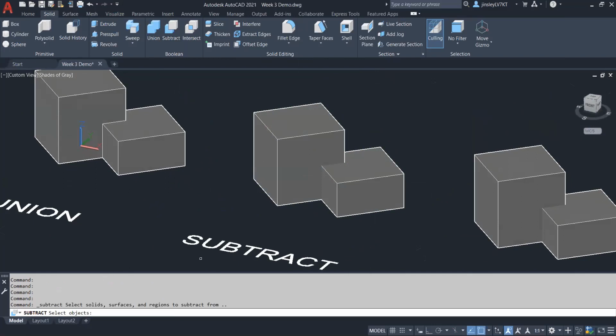So if you read the command line up top here, it asks us to pick the objects that we are subtracting from. So you're picking the part that will stay. Okay, I want this big block to stay, so I will pick this. When I'm finished, I can hit enter to go to the next step. And now it's going to ask me to pick the solid surfaces and regions to subtract. So what part do I want to remove? Okay, I want to remove this small piece.